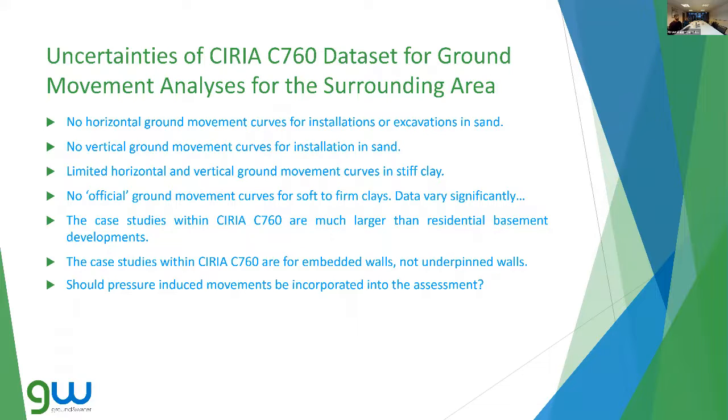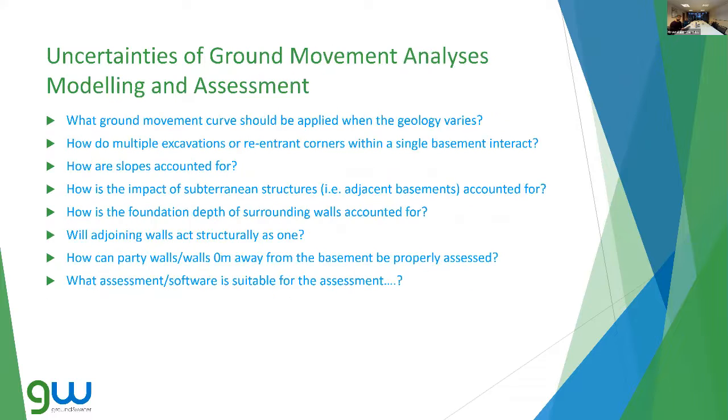Another point of note, obviously this depends on what analyses you're doing: should pressure-induced movements be incorporated into a ground movement assessment? Basically, the previous slide where we talked about settlement and heave analyses, should the resulting displacements from those models be used in your ground movement assessment models? Now moving on to the ground movement assessment models themselves, there are some, but based on the type of modelling that you're doing,